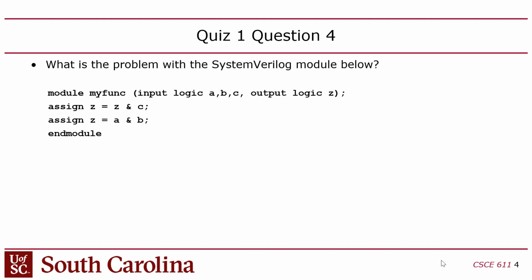So every time Z is updated, it re-triggers and changes Z potentially. So it's not smart enough to catch that? No, actually it's not, believe it or not. I think there might be an option, but it used to be when we used VHDL, if this happened, you would get an error message that said iteration limit reached.